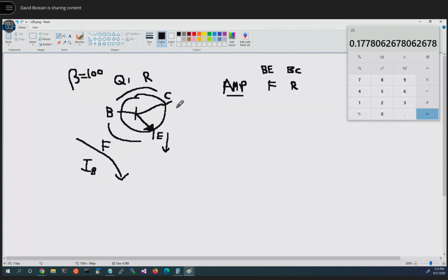And then it takes and produces a current which comes in the collector and goes out the emitter, which is basically 100 times, or beta times, IB. Little current in here, big current passes through the transistor. So you can think of it as though it's a gate that we're opening up a little or a lot, and the current here is following with this multiple number of times.